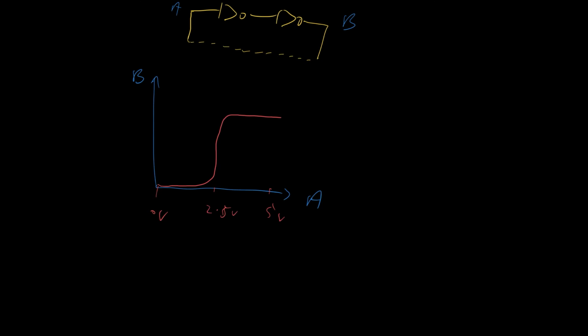As we will see presently, it's most useful to draw a line at 45 degrees through this graph here. And this allows us to work out how this circuit works. Along this dotted line, imagine that there's a small delay. So we put a voltage at A, it propagates through to B with or without a delay, doesn't matter for this argument. Then there's a small delay before being fed back to the input. And so this means that this circuit could oscillate, or it might converge to an equilibrium point.